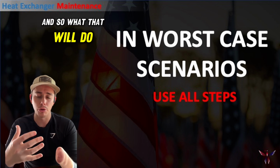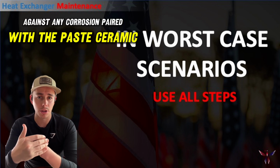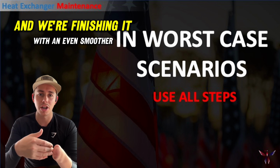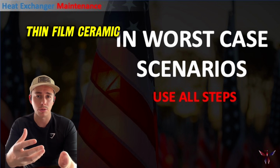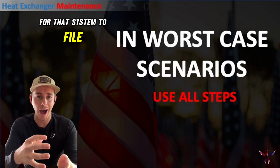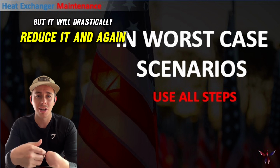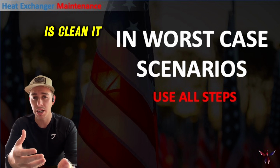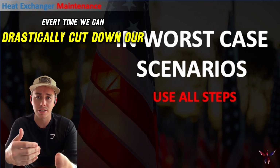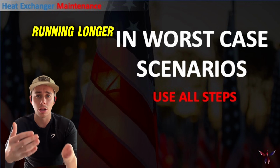And so what that will do is, 1, provide a barrier against any corrosion paired with the paste ceramic. And 2, because we now have a smooth surface and we're finishing it with an even smoother thin film ceramic, we're going to drastically reduce the ability for that system to foul. It doesn't mean that we can't have some, but it will drastically reduce it, and again make it so all we have to do is clean it, as opposed to do a full rework on the system every time. We can drastically cut down our overall maintenance of the system and keep things up and running longer.